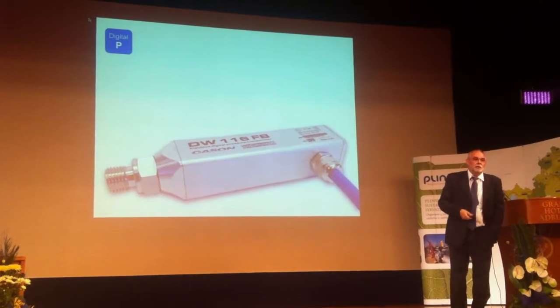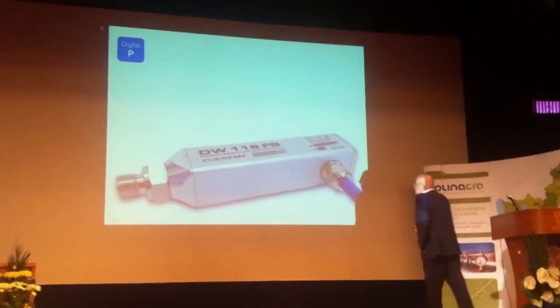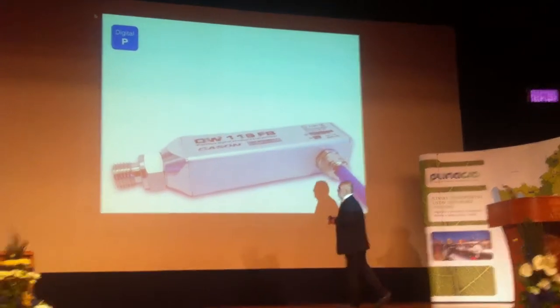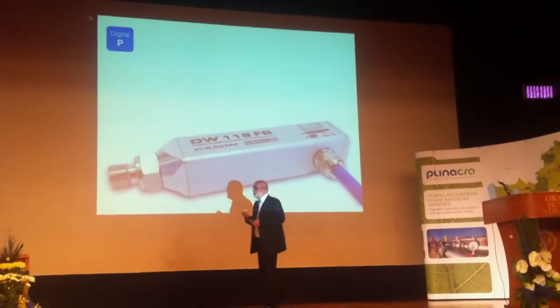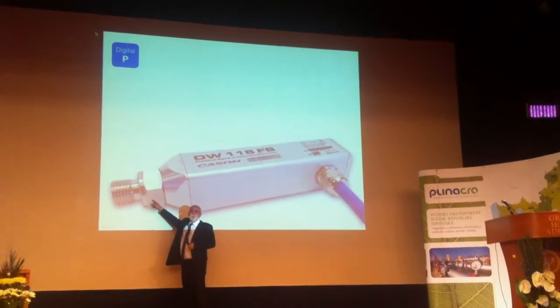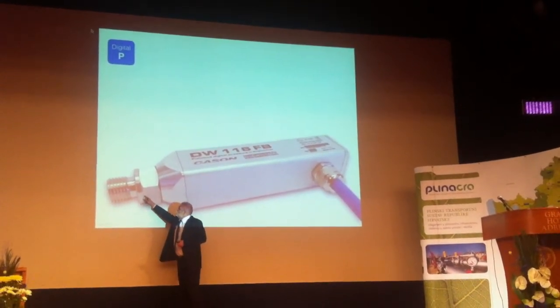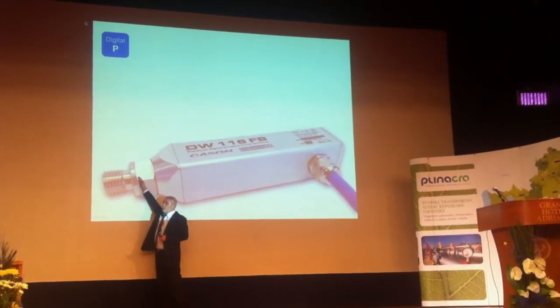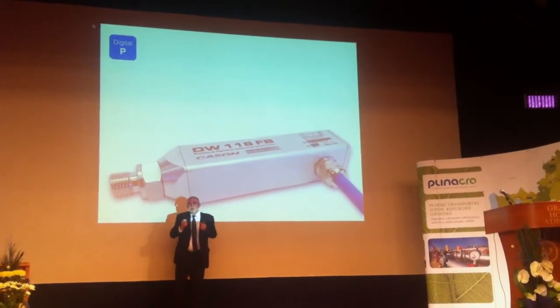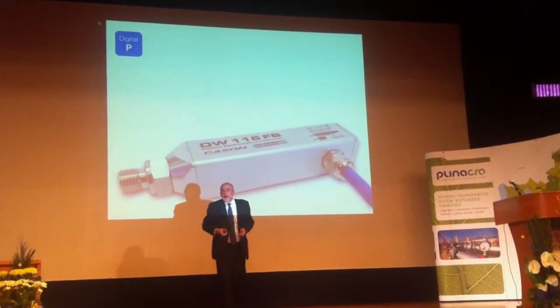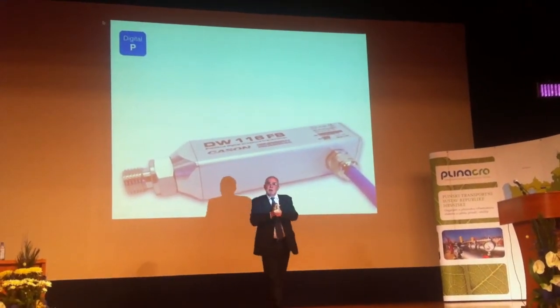Just talking about pressure sensors. There's a new, very interesting change in the world. Digital pressure sensors, not transducers but sensors, are on the market already, which means that from the interface, it senses the pressure. I already have a digital signal, so there is no analog processing anymore, which means there is no calibration anymore.